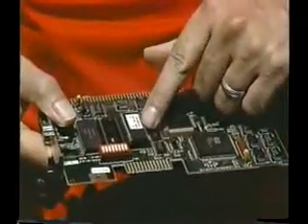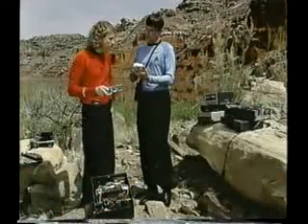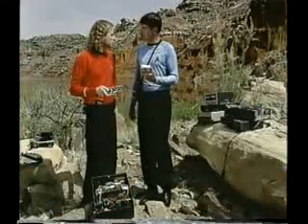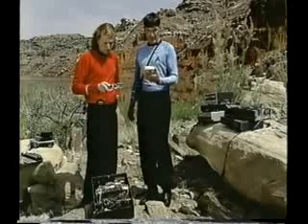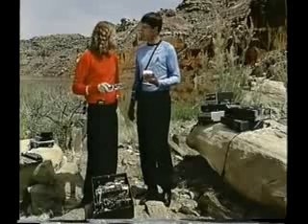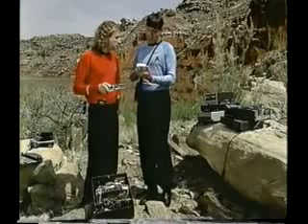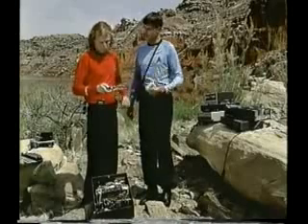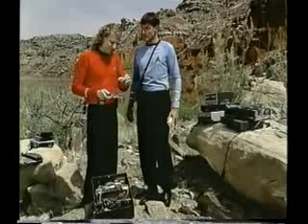The DIP28 appears to be in some kind of holder. Fascinating. That is a socket. Sockets are soldered on the board just like components. This allows the IC to be inserted and removed without soldering and desoldering. Try gently removing the IC. There we are.